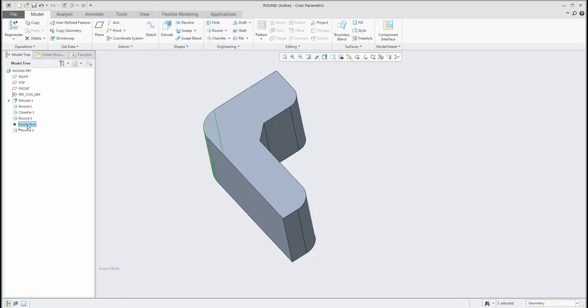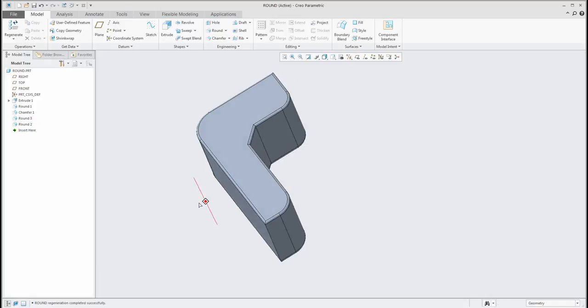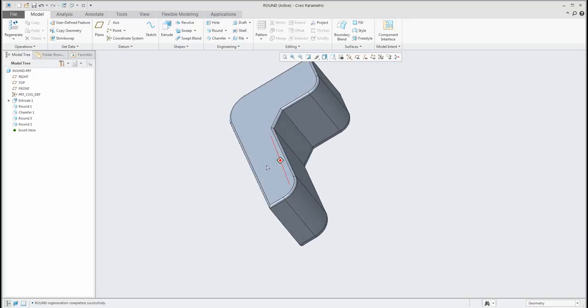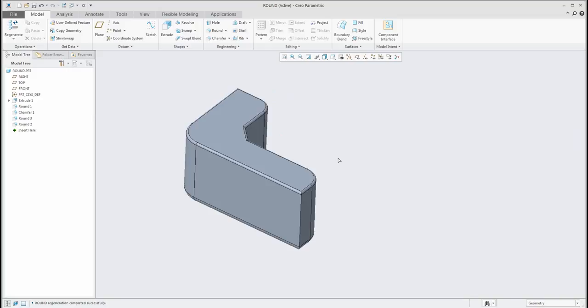And right now, if I move the insert here, the system creates a round feature on the surface connected edge. So again, I like this function, I use it many times: I select one edge and then the shift button and a surface, and the system will create the round feature on the other loop.